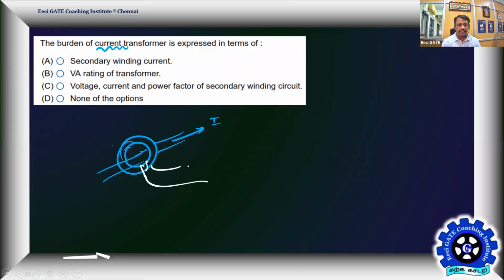This is where we are going to have the ammeter. Assuming it's an AC current, we're going to have an AC ammeter. This is the current to be measured, maybe 0 to, for example, 20 amps. So you can step it down, for example, to 0 to 1 amp. So 20 times you can step down by using a CT, to a safe level.